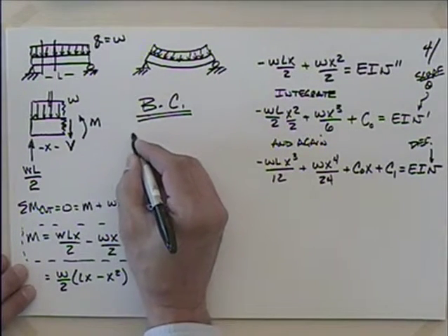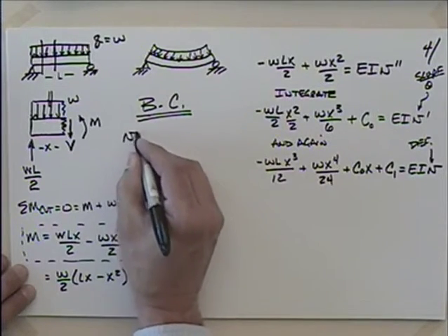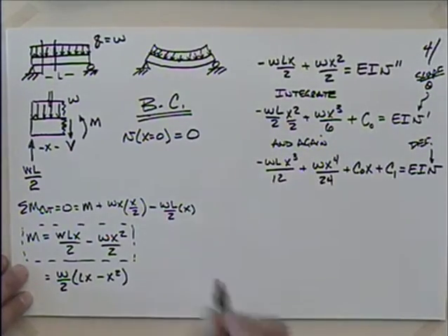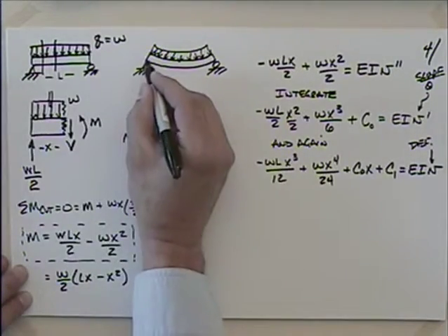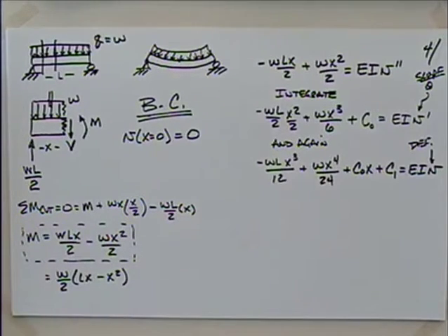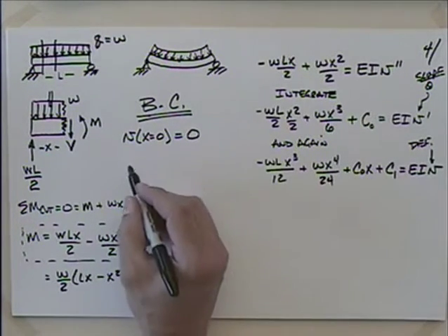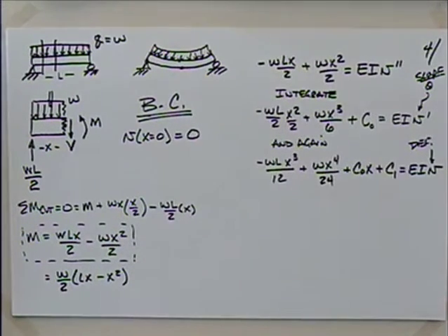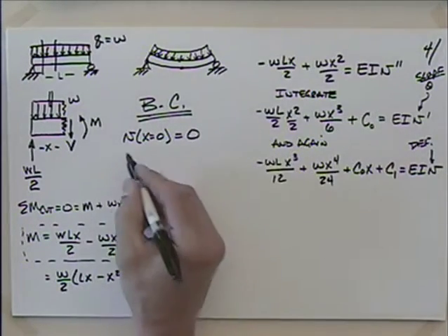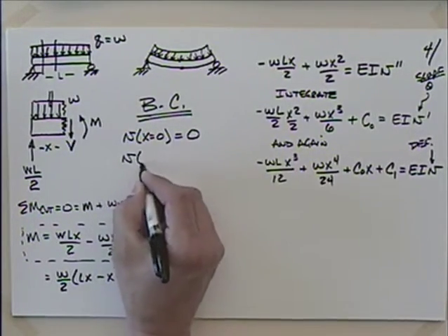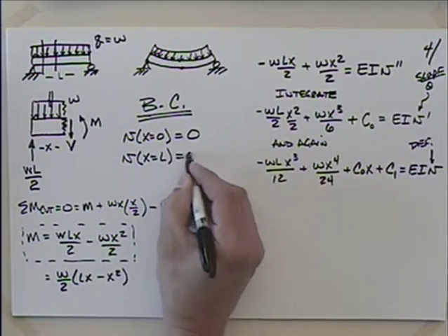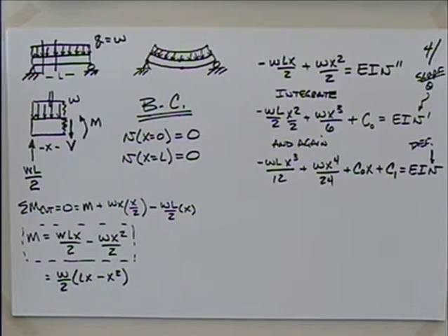Okay, great. The deflection, v at x equals 0, is equal to 0. So he said that over here, there's 0 deflection. Absolutely true. There's probably maximum deflection in the middle on this one, although I don't know what that is. That's probably not a very good boundary condition. But as I continue looking across this, what is a good boundary condition? At x equals L, what do we have? 0. Okay, so those are a couple good boundary conditions.